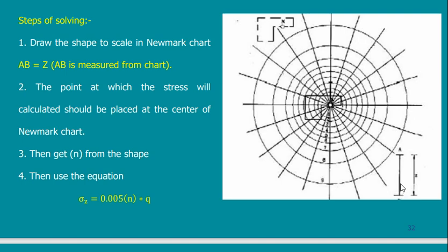In your calculation, you want a depth of 5 meters. In this case, I want a scale where each 5 meters is represented by 5 centimeters. So 1 centimeter represents 1 meter. So it is a scale of 1 to 100.